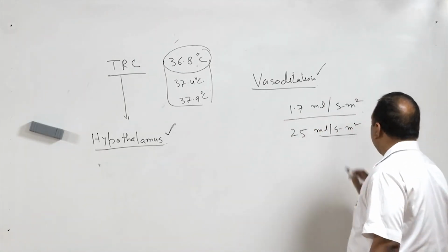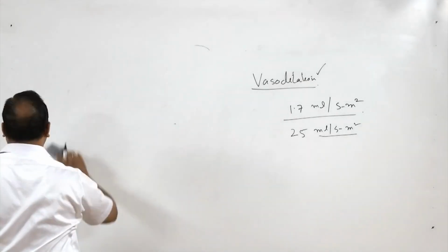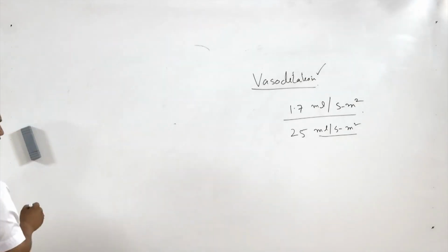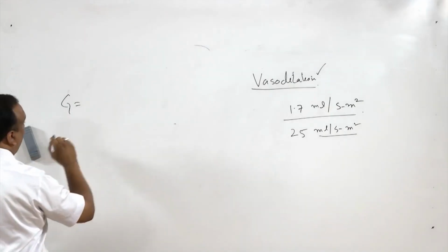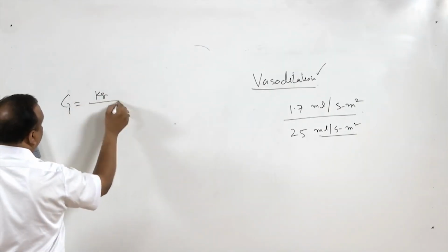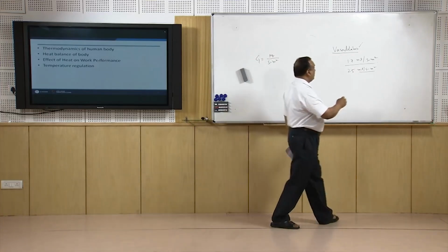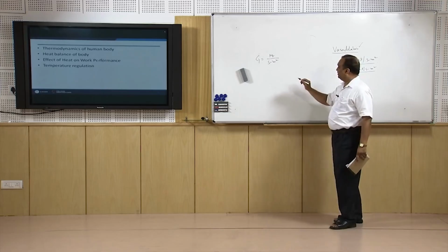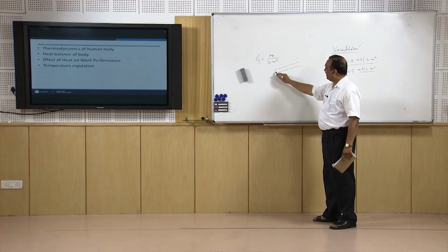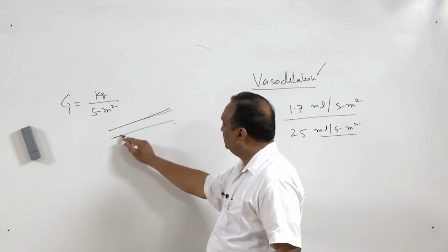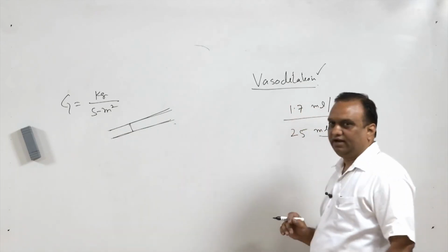Now, why am I writing per second per meter square? The reason being, in many fluid mechanics analyses, especially two-phase flow analysis, the mass flow rate or mass flux is expressed in kg per second per meter square. And this becomes important here, because in engineering practice the passage has a rigid wall. If we are analyzing flow in a pipe, the pipe has a rigid wall, right? So, the cross section area of the pipe is constant, and we can do fluid mechanics analysis on this pipe.